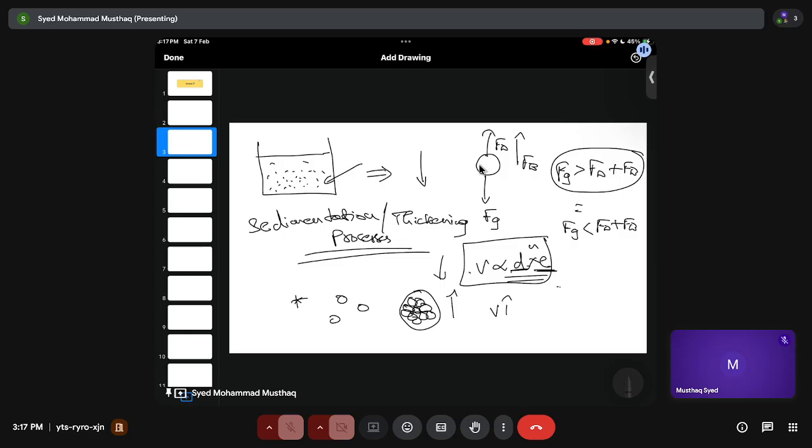Now how do we do that? There are two ways. Either you coagulate, or you flocculate, which we covered in previous assignments. Now let's talk about coagulation first. What happens in coagulation? It's more like an agglomeration, where fine particles come close together and attach. For the surface forces to be dominant, whether van der Waals forces or London van der Waals forces, these forces must be dominant.